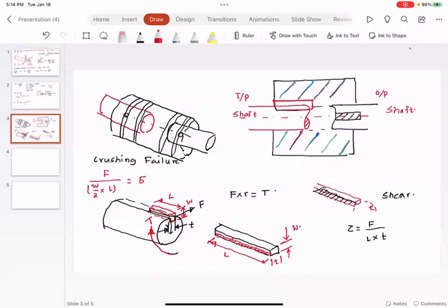So coupling is a hollow shaft. Do you agree with me? So you would design the coupling by means of hollow shaft design. Please understand, as soon as you design the shaft, the inner diameter of the coupling is designed. You cannot have a shaft diameter different than the coupling inner diameter. So the outer diameter of the shaft will be the inner diameter of the coupling, and then to determine the outer diameter of the coupling, you would use the equation for hollow shaft. Everyone understood this?